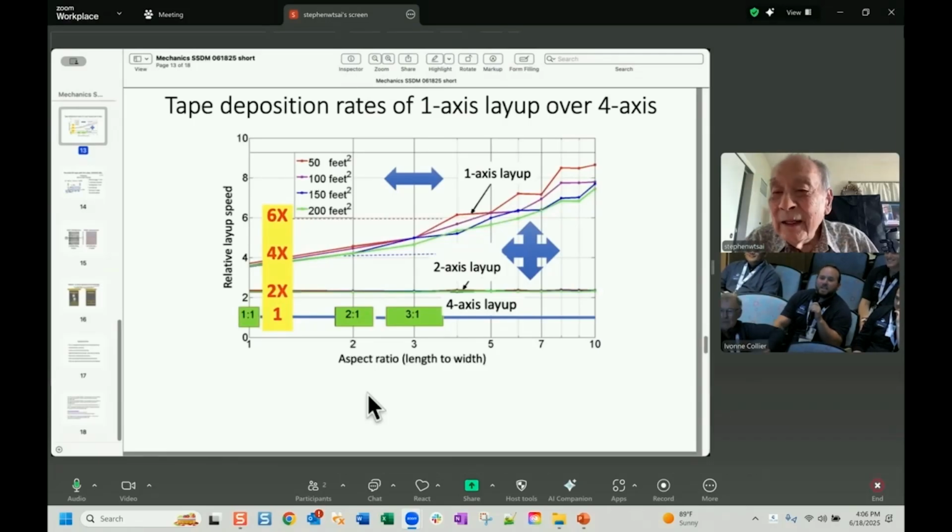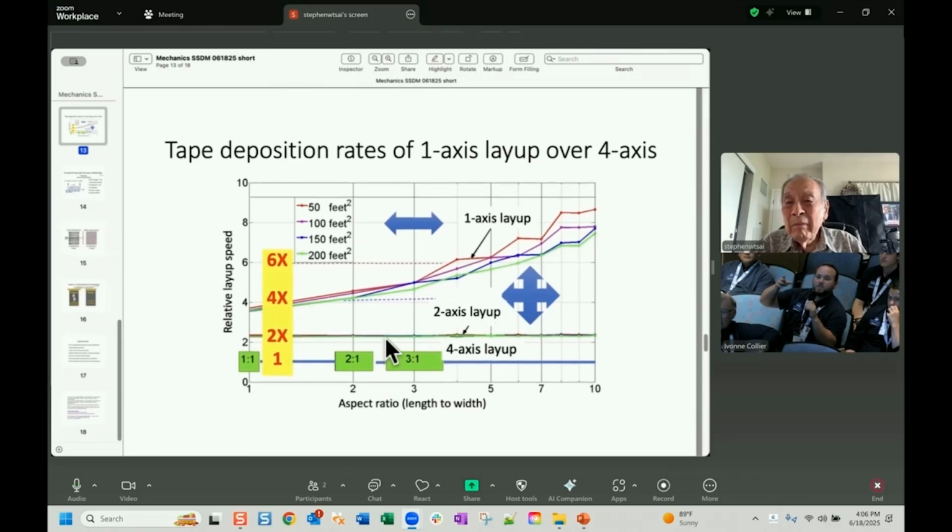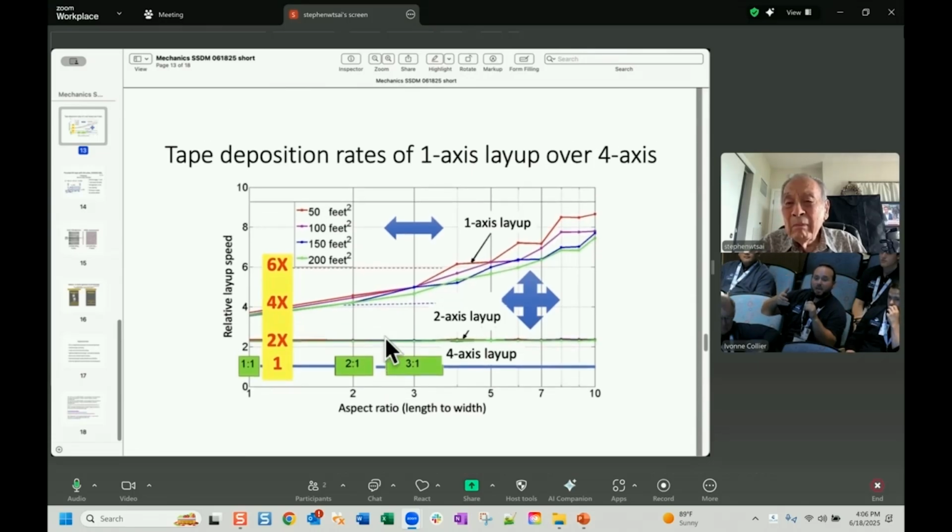You showed in one of your slides that one of the benefits is that you're not dropping or adding any plies in the middle of a laminate. Often in fabrication, and especially in HyperX, we give the users the ability to do a study between how they want to do the layup. Do they want to do it interleaved? Do they want to do an hourglass? Do they want to do a diamond? Is there any benefit to those different sizes using the double, or do you just always recommend to do it as a pyramid and drop the outside plies as needed?